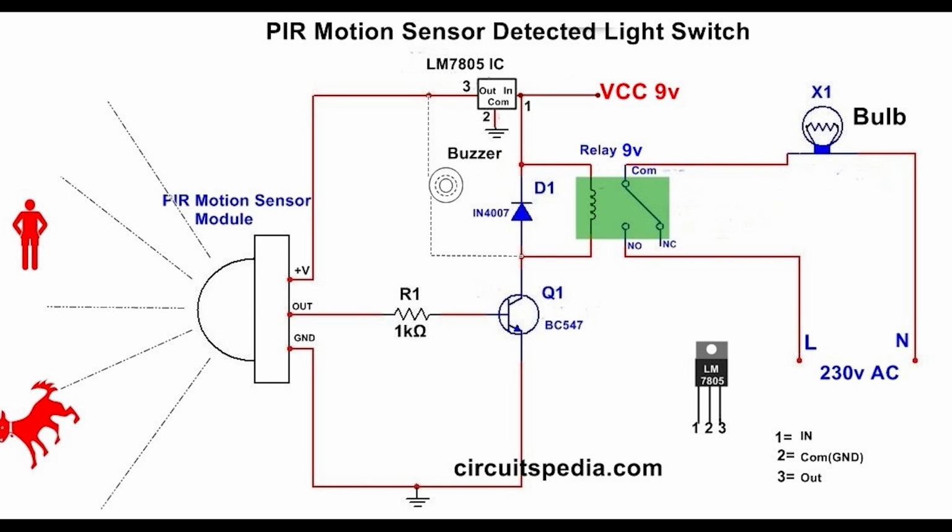Then the 5 volt one, I think the maximum rating is around 18 volts. However, you have plenty of headroom to power this up using any 12 volt power source. But the question is, this IC is used only for this PIR motion sensor. So the motion sensor has V plus and ground connections. It has output signals, so you can amplify using a common NPN transistor. Then, what if you are powering up a relay?